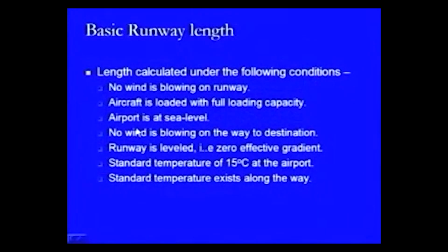Another assumption is that the airport is provided at the sea level, because at the sea level the meteorological conditions are at its standard. So, with respect to those standard values, then whatever variations are there, we will be considering those variations while calculating the length of the runway strip. So, this is another assumption.